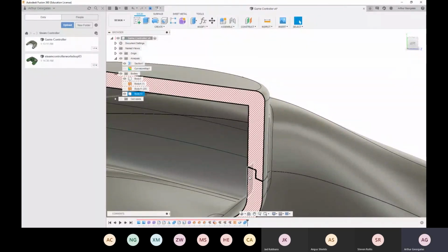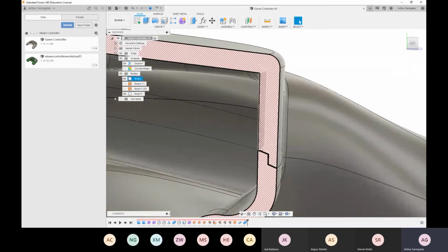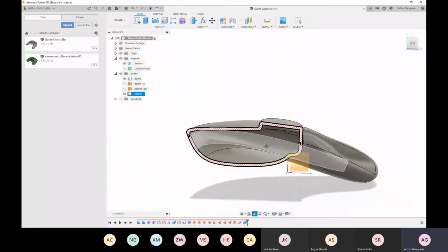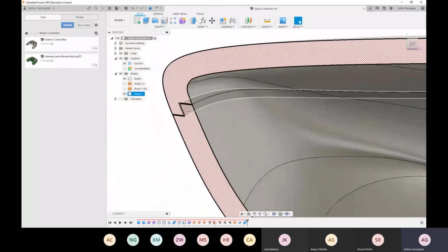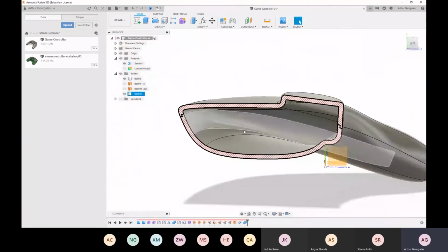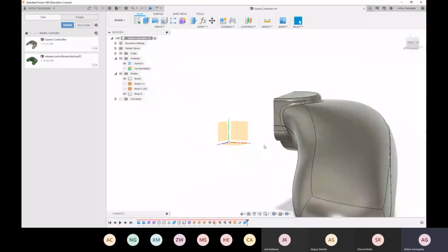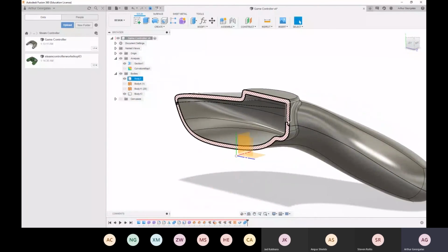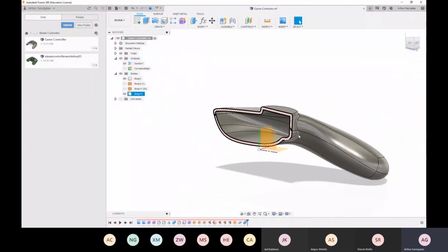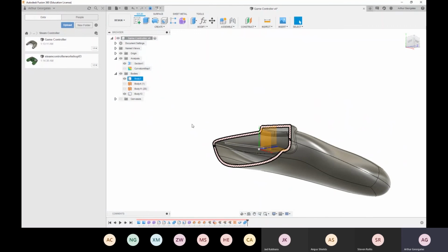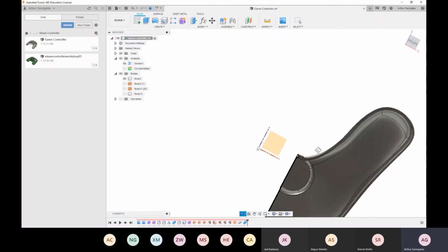That's pretty much, why is that not working? That's pretty much how we're going to go. We want to do a lip and groove. You can have it like this. You can have one where it's got just a tongue in the middle of it, but generally this is fine for injection molding. It can be really tricky to get these parts consistent. But you can have a tiny bit of overmolding on those bits just because it starts to get quite thin and flexible. So it can usually be removed from a mold without any problems.